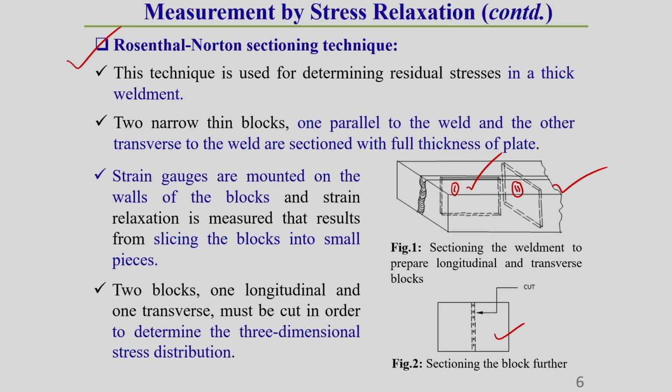Here one thing you should keep in mind: previously, in the case of the hole drilling technique, whatever formulation I have shown, that is generally stress and strain, whatever we measured. So, by using that formulation we will measure the principal stresses, that means the maximum residual stress and minimum residual stress, as well as the stress in different directions in that plate. And through the thickness also we can measure the residual stress distribution, depending upon the position of the strain gauge. This you should keep in mind.